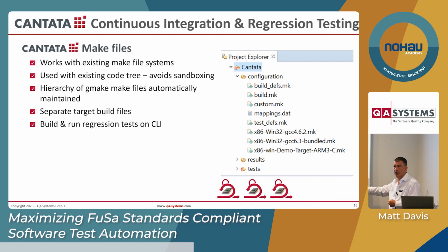If you are doing a Class A device or an ASIL A system, you can run all your tests host native. You don't even have to use a cross-compiler. But if your application is very heavily dependent on the physical environment, it's a lot of effort to have to simulate all of the behavior of that hardware, so you might run it on the target because it's faster and more efficient to do so.